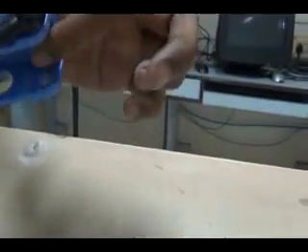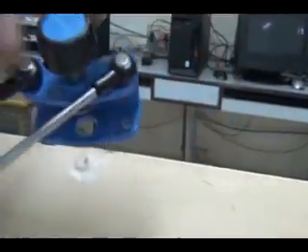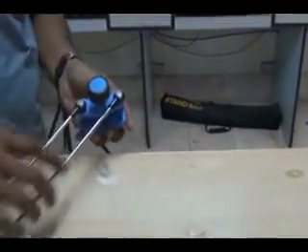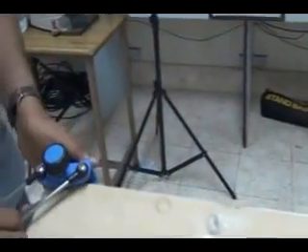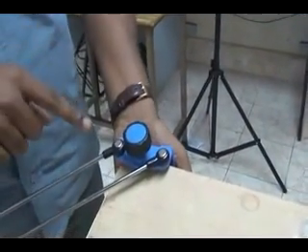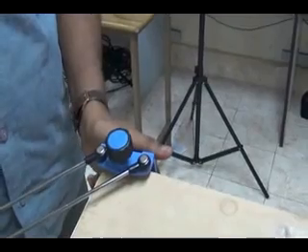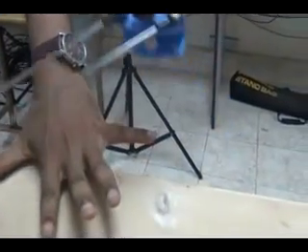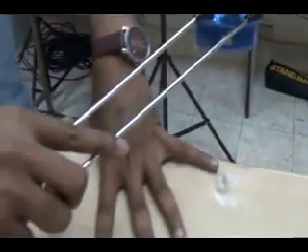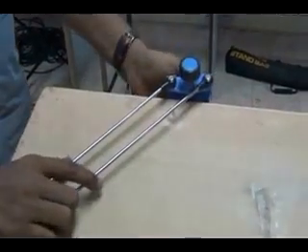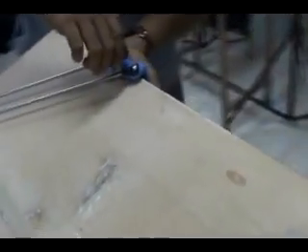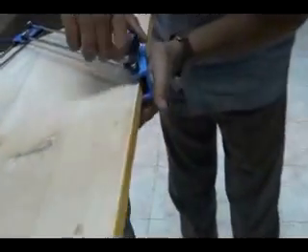You see that holder, inside I have a flat portion. That flat portion has to exactly match the flat portion of your drawing table. You see how I am fixing it to the left extreme. You should not fix it at the left extreme; you have to leave a gap. Then you have to fix your drafter. How I am fixing, you see.